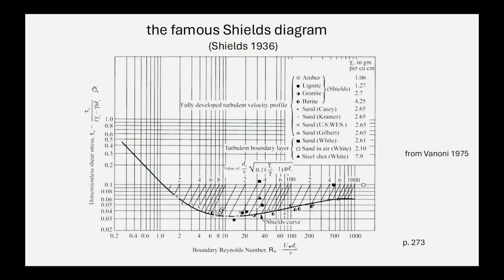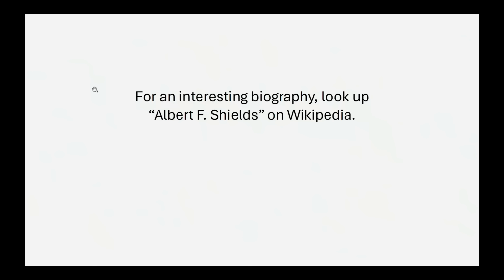But when you get down to really fine sizes, they dominate the situation and the particles tend to clump together. And so that makes it more difficult for the flow to move. And although there's no data here, that's a reasonable way of looking at what happens in fine sediments. You have to really have a strong flow to overcome those interparticle forces.